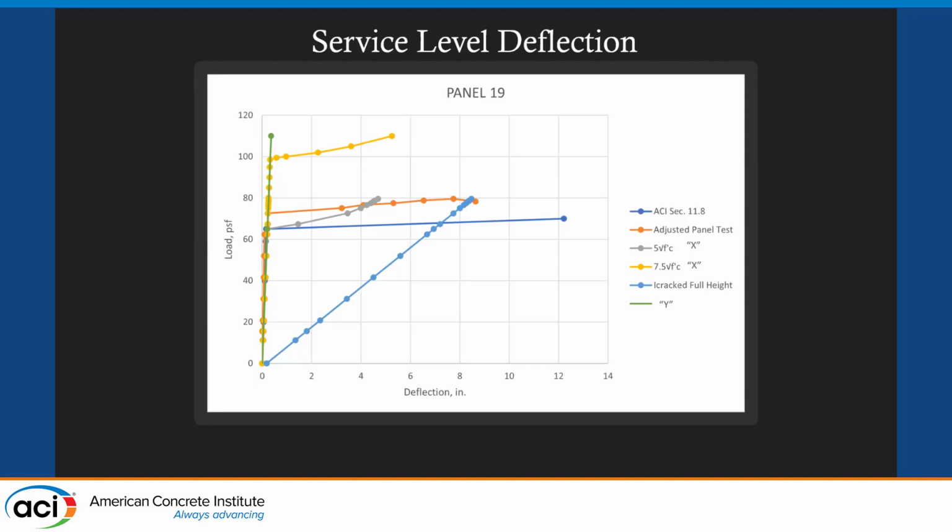Here is just to show that if you were to choose I cracked full height within software X, assuming that the section is cracked from the start, is why you see no immediate stiffness reduction, because it's just a constant deflection based off of loading. Also, one more thing to note is that software X uses the Bischoff method, which you can see here with this curve.